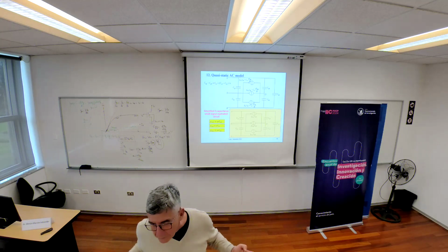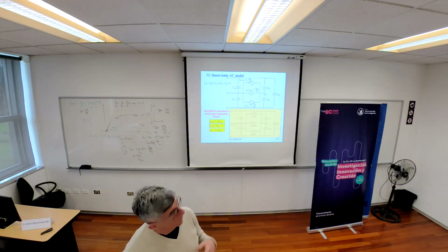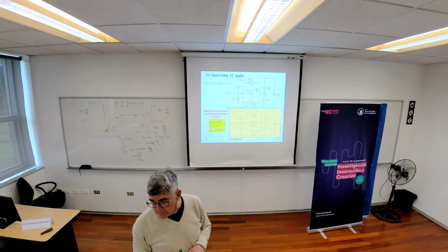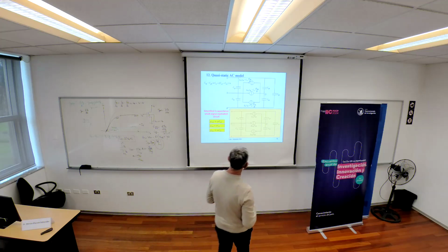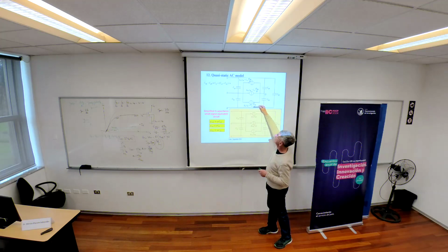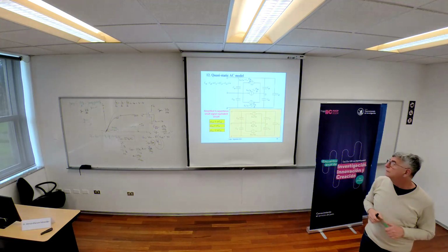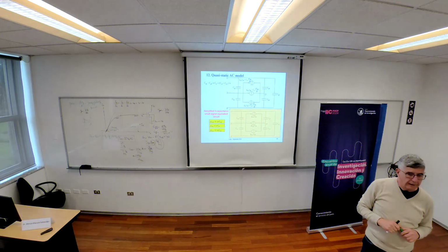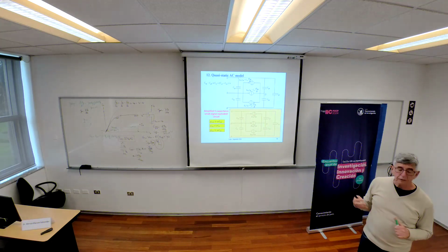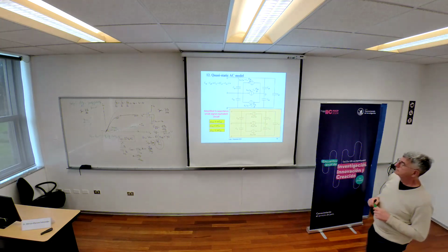It's for frequency reasons, because we usually don't solve this problem for very high frequency. After removing what we call transcapacitances, we finally find the AC model that is appropriate for solving almost all the AC problems, or problems associated with small signal analysis.